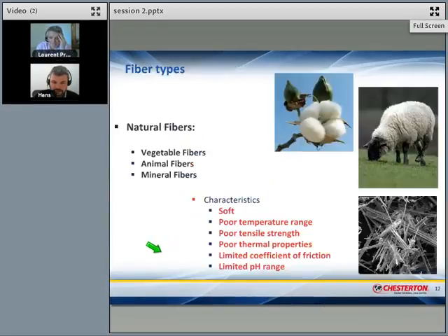Now imagine that I take my sock and I take some grease and I completely fill this sock with grease, and then I use it as a packing. Well, this grease actually does two things. It reduces the friction of my sock on the shaft, and as well, it will stop water from going through the fabric. It becomes like a barrier. Okay, good. All right. Thank you.